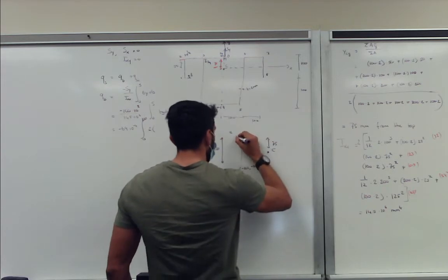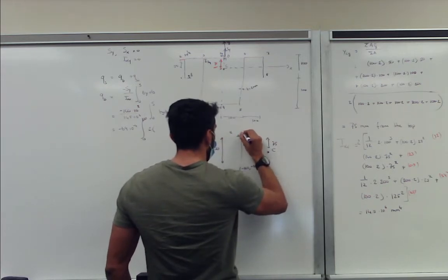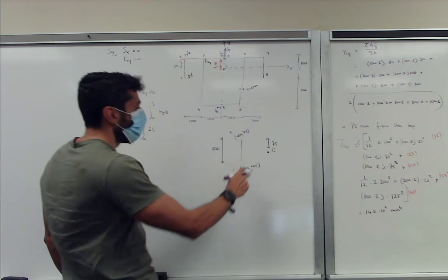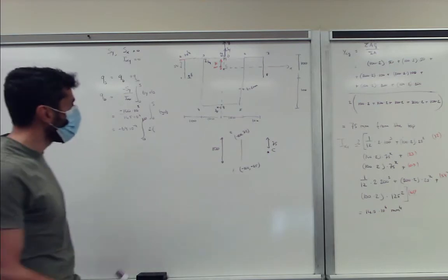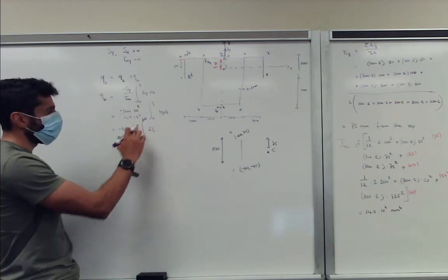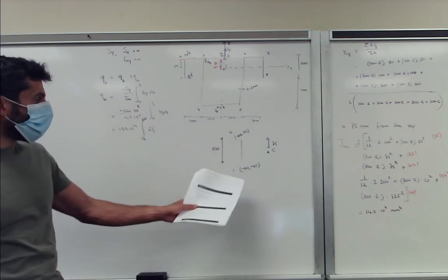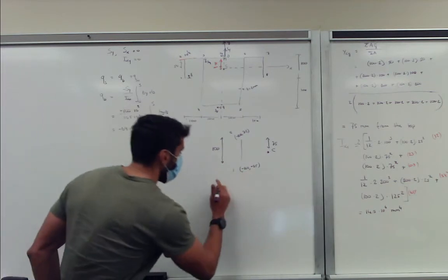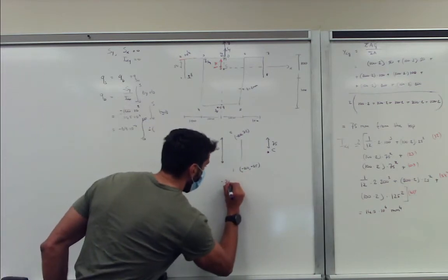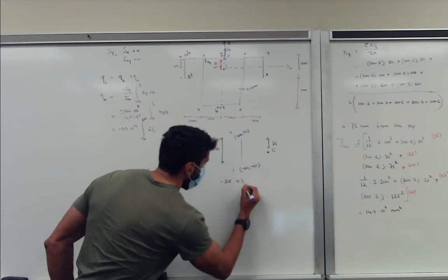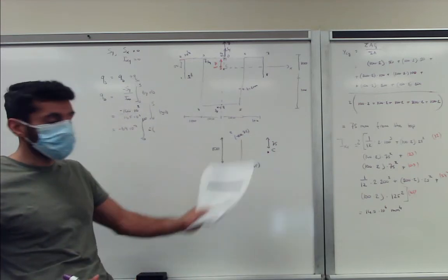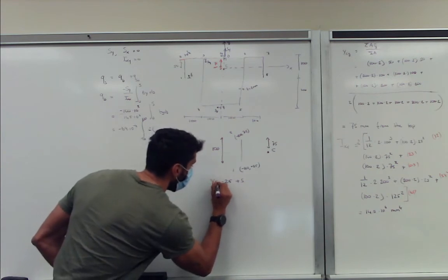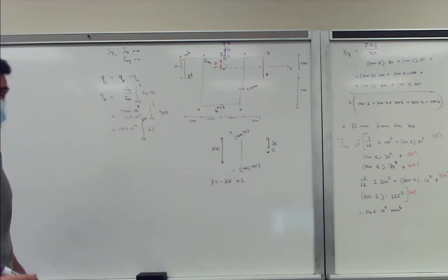And this coordinate is minus 100, comma, 75 from your centroidal axis. So our distance goes from 0 to S. If we start out from minus 25 and add S, going from 0 to 100, then we get our coordinate. So y is defined as y equal to minus 25 plus S.